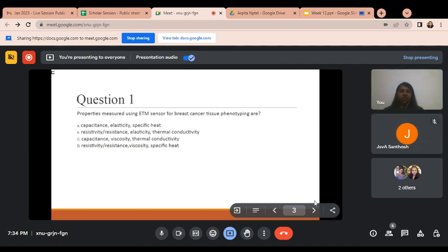Okay. And also in that case we use the photoresist. Have you heard about positive and negative photoresist? Yes, ma'am. So can you explain? In positive photoresist, it is able to maintain its size and pattern in the photoresist developer, and the solvent doesn't penetrate the areas that have not been exposed to UV light.